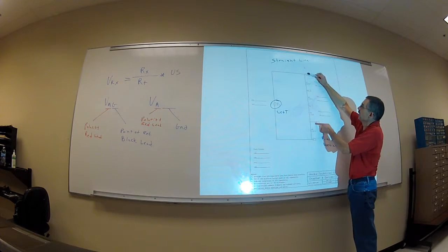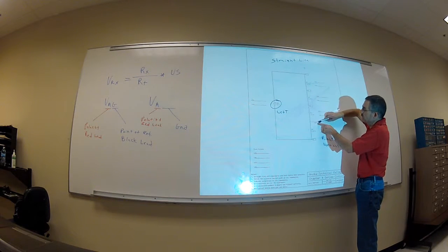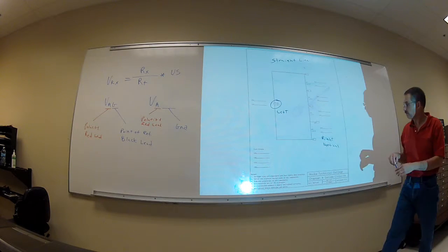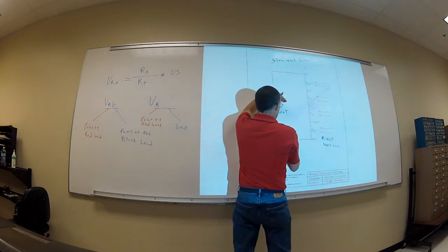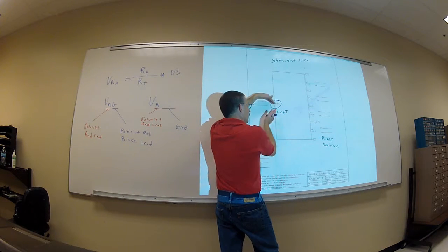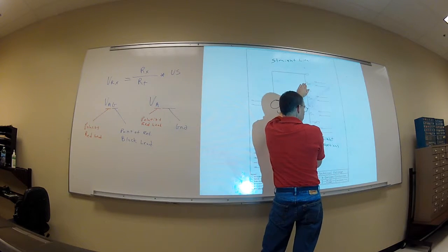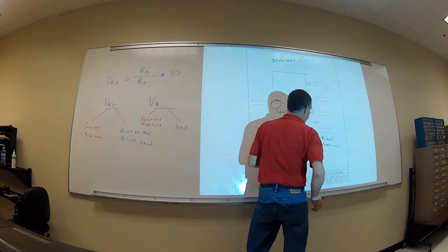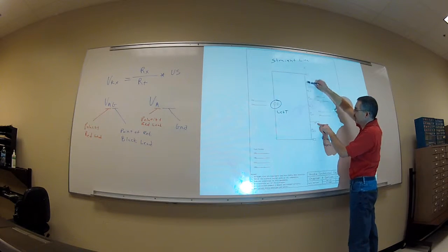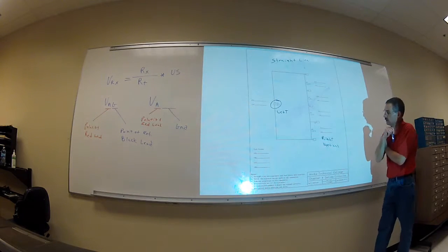Because now I can just identify my test points, going right down. I have the same number of components, but it's a lot easier to analyze going this way. It's a lot easier to see what's happening. And so we call that straight line. When we get into chapter 6, we're going to be straight lining all our circuits: redraw them, put the power supply on the left-hand side, all our components on the right-hand side, and draw them all vertical. Then when we're analyzing them, we're just going straight down, boom, or up, depending on referencing it to ground.